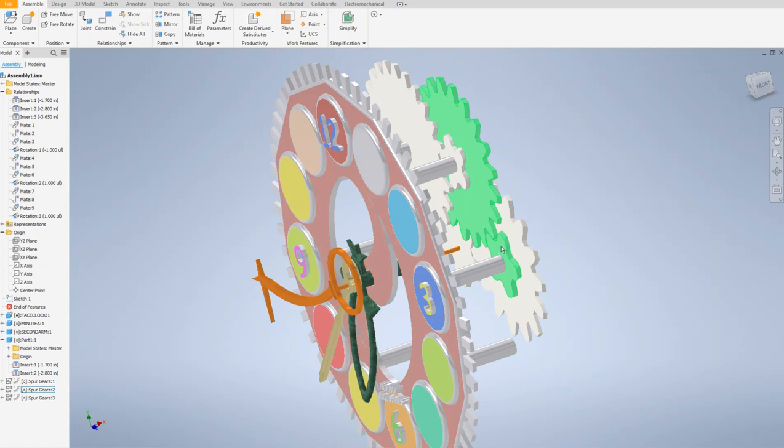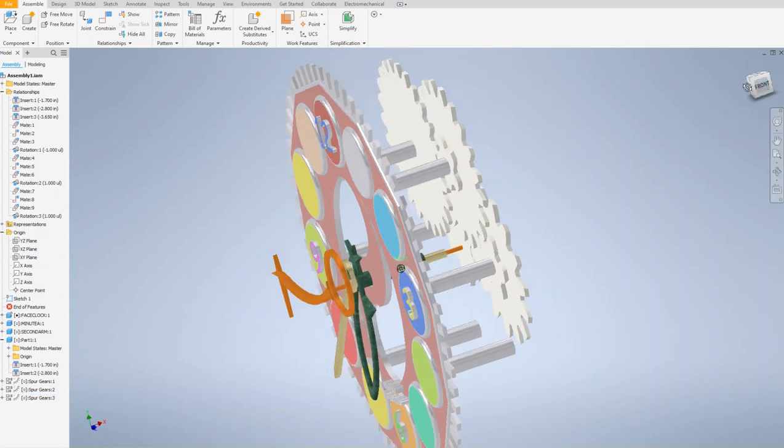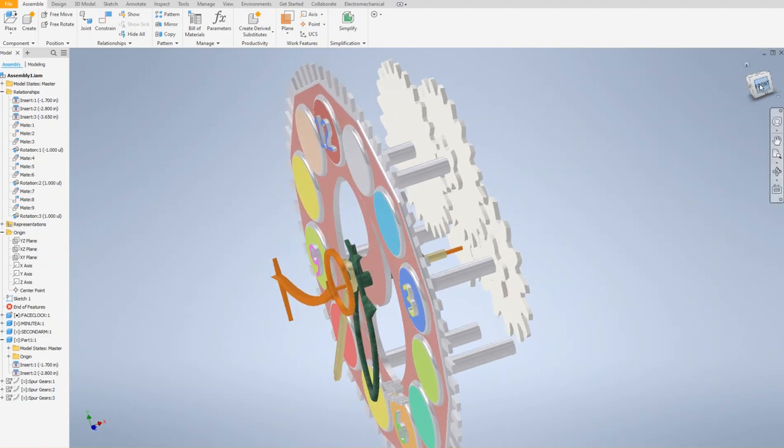That smaller gear, this time, operates a much larger gear, with a mechanical advantage of 4. So whatever the number, 5 teeth times 4, 20 teeth over there. So any large gear is connected to a smaller gear which rotates it, and the smaller gear is meshed into the much larger gear. This is the way the second arm operates.